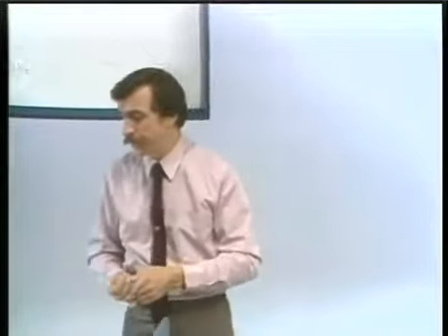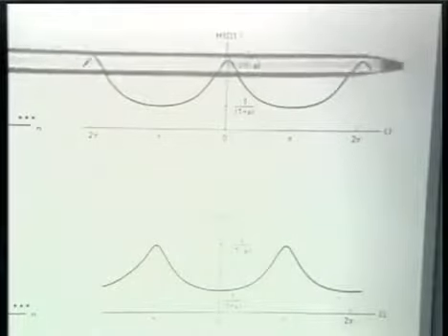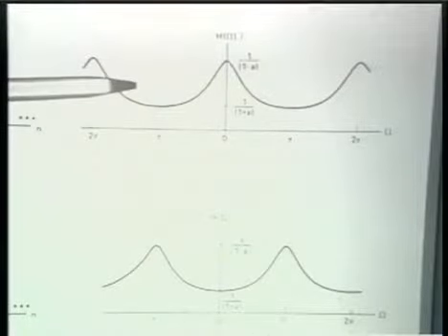We'll process the Dow Jones Industrial Average through a first-order difference equation. If we begin with A equals 0, then referring to the frequency response that we have here, A equals 0 would simply be passing all frequencies.